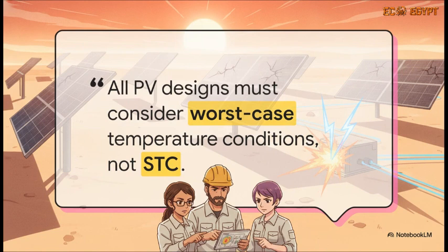Before we wrap up, I want to leave you with this critical piece of design philosophy. Standard test conditions are great for a lab, but they will fail you in the real world. You must absolutely always design for worst-case temperature extremes to avoid inverter overvoltage and guarantee realistic energy yields.